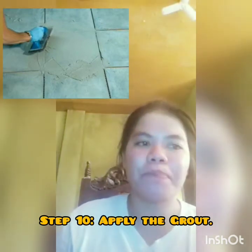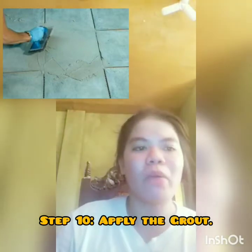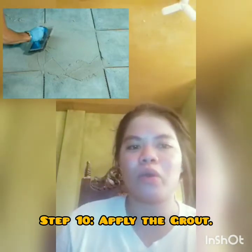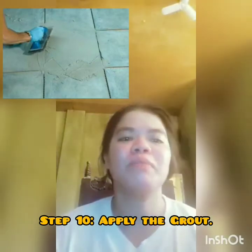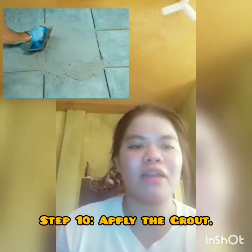So, last step is remove excess grout. When the grout is in place, wipe away the excess with a damp sponge or cloth. Repeat this process several times, being careful not to remove the grout line around the tiles.